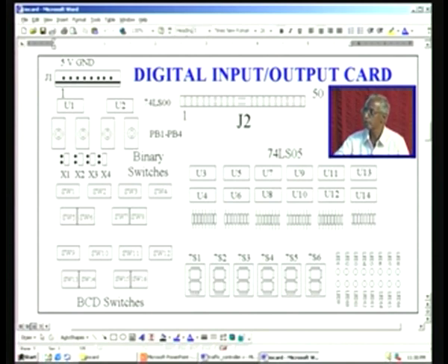And if you notice this, we have a 50 pin connector, of which we need VCC and ground, that is plus 5 volt is connected to pin number 1, and pin number 2 is ground. And pin number 3 starts with this segment A, and it goes until the very end, 50. So, you can see that the difference is 2, if you knock them off, what you have is 50 minus 2, 48, and that is precisely what you have here. So, 6 into 8 is 48, and in the very same order.